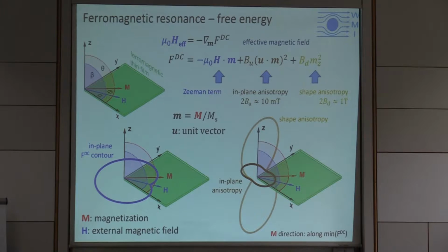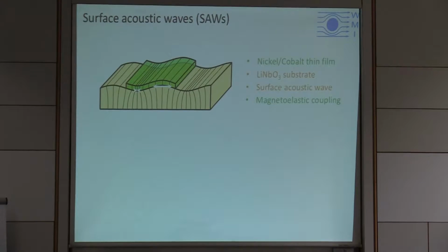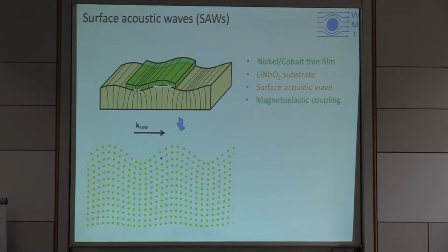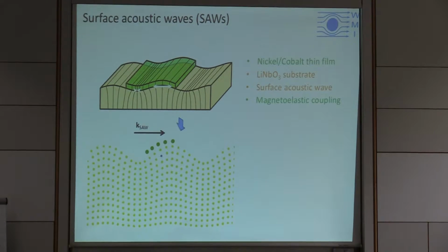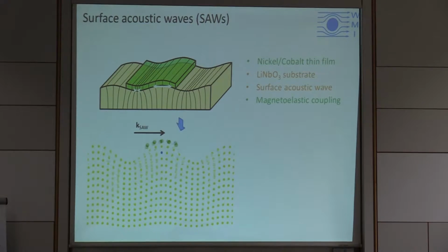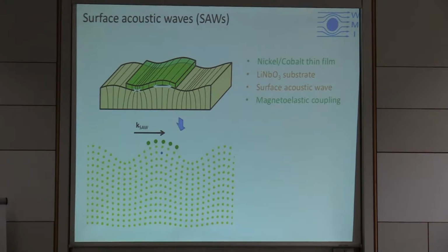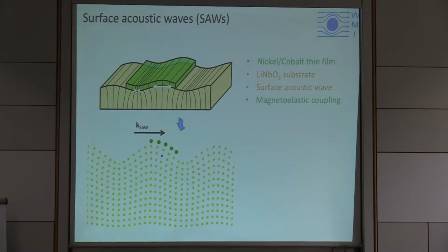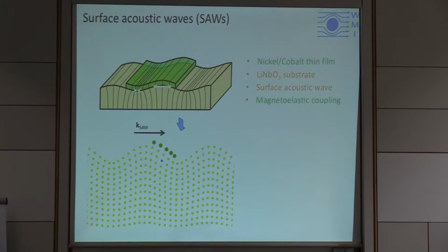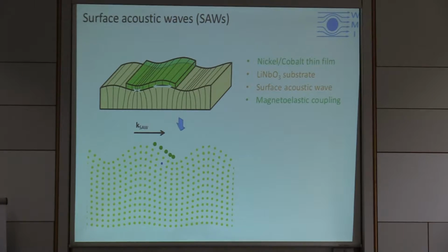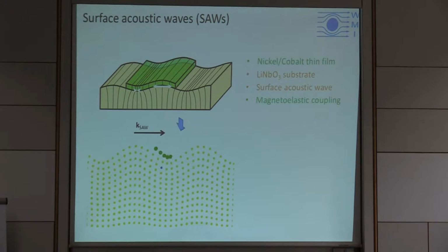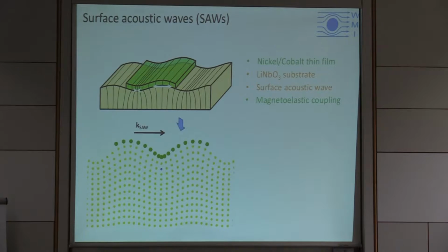We want to introduce now, or bring, the surface acoustic wave into the concept, and the idea is literally to deposit this magnetic thin film, which should have a magnetoelastic component, onto the surface acoustic wave, and we employed Rayleigh waves for this context. And you see already the typical animation of the surface acoustic wave, and you deposit your green thin film on top by evaporation and modulate now the stress by periodically stretching it and compressing it. So you have a modulation of tensile stress and compressive stress onto your green ferromagnetic film. And to be honest to you, the film extensions for our films were typically larger than one wavelength.